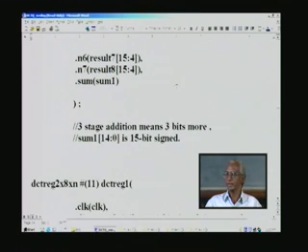After truncating this many bits, we always compute the PSNR, or what is called the image quality, and compare it with the corresponding MATLAB output. If it is quite close, say of the order of 0.5 dB, which is roughly 2% accuracy or less, then we truncate accordingly. So that is how we do the truncation here, and here there is a 3-stage addition.